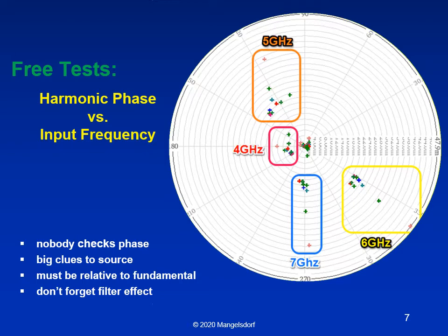Okay, when it comes to looking inside the silicon to look at how the ADC is performing, the spectral performance, this spurious free dynamic range in particular, are very important in all kinds of signal processing these days. And so it's important to check the harmonics.